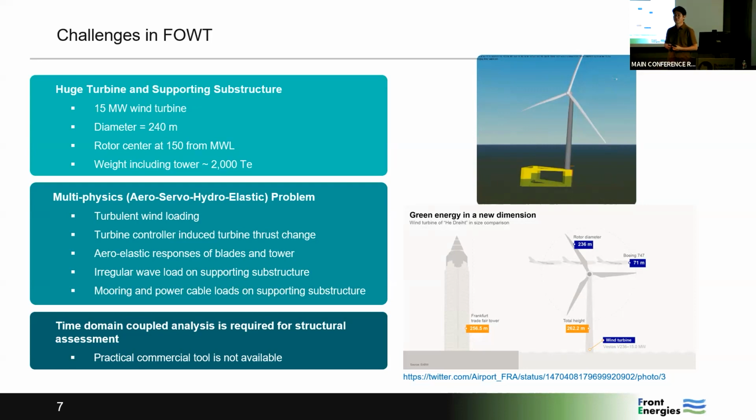How impractical? Even for a simple semi-submersible structure, a 1 hour simulation with a time step of 0.1 second takes a commercial tool a day or a week to solve. It's impractical because we need to do this time domain analysis for 2,000 or 4,000 cases. So one single run taking one day or one week is impractical for engineering analysis.